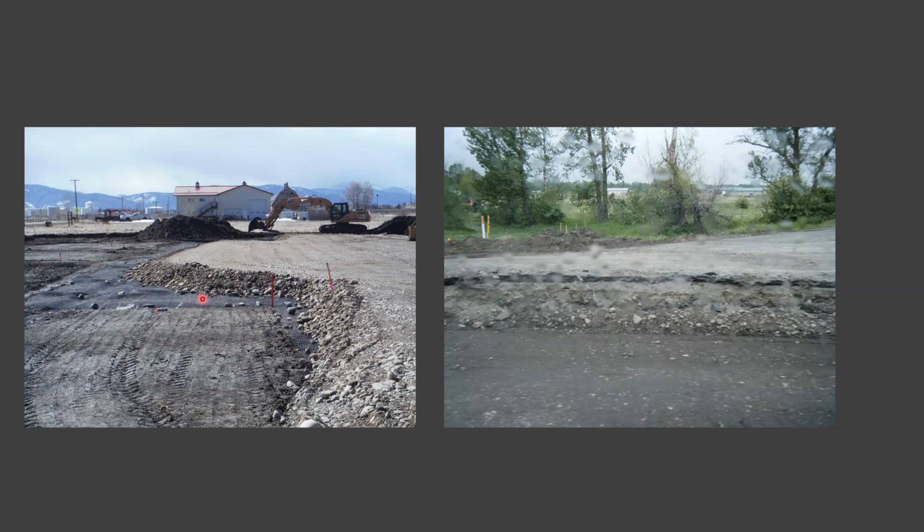On top of that, they're laying some sort of coarse geotextile fabric, and then it looks like a good 18, possibly even 24 inches of pit run before they start to bring in crushed gravel for a nice base course. But this compacted subgrade and also this sub-base material both had to have in-place density tests run on them. Every layer in this kind of sandwich has to be tested for compaction.